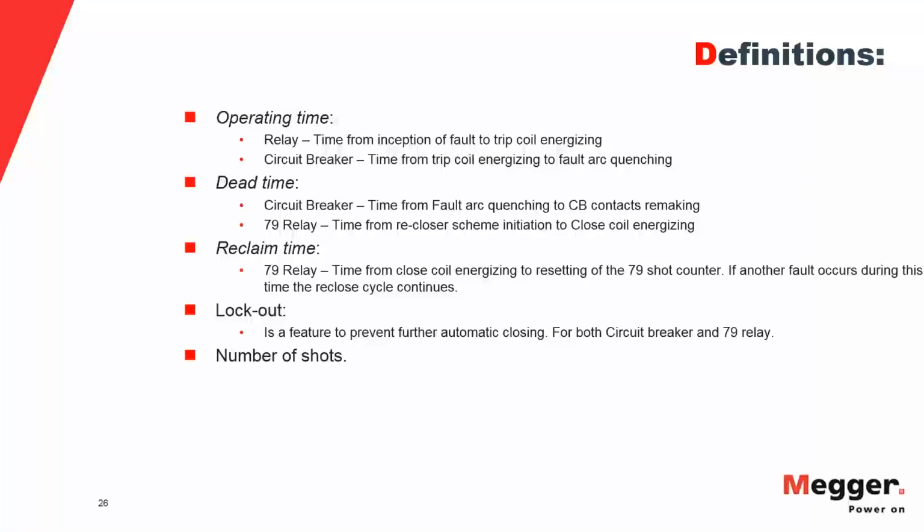Usually for reclosers, the first and sometimes even the second shot are fast shots, and then the third and fourth, if there are that many, are usually slower, either because you want some fuse down the line to burn, as we'll see later, or because you want to give more time to whatever is between the lines to burn itself, right?